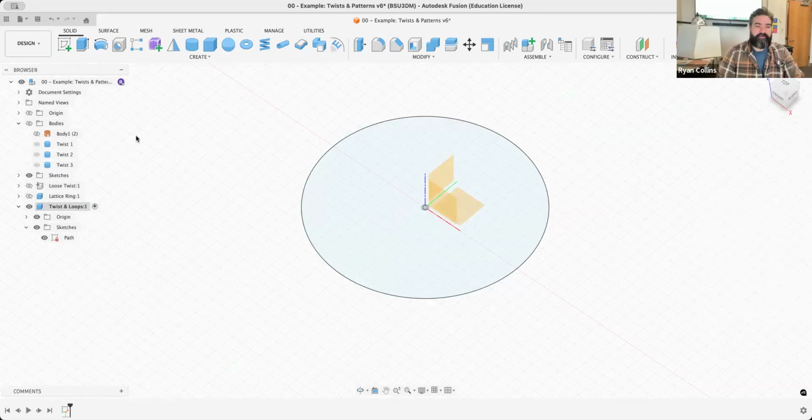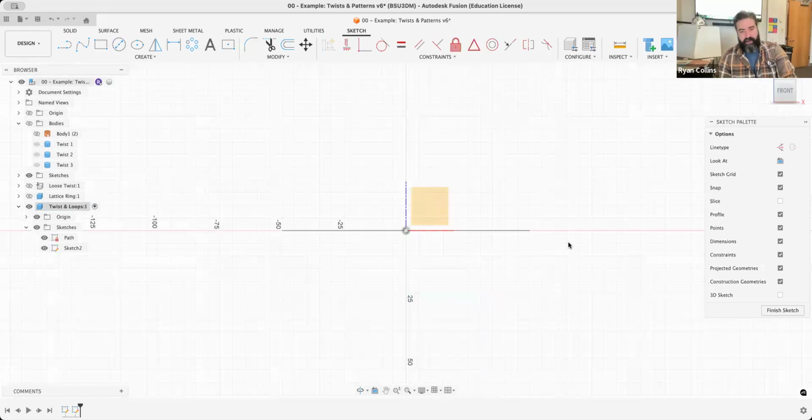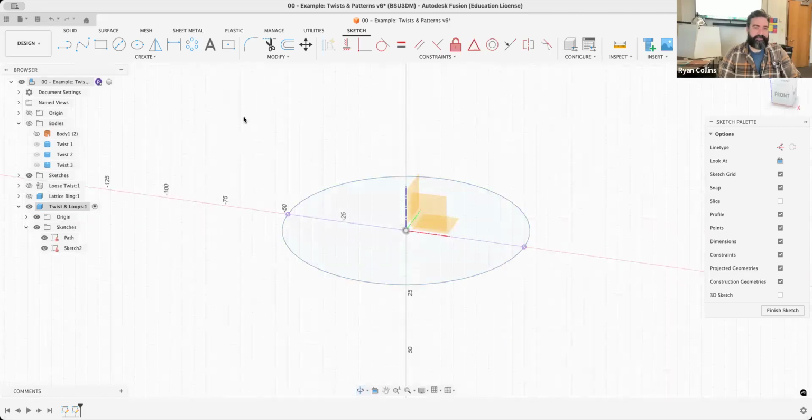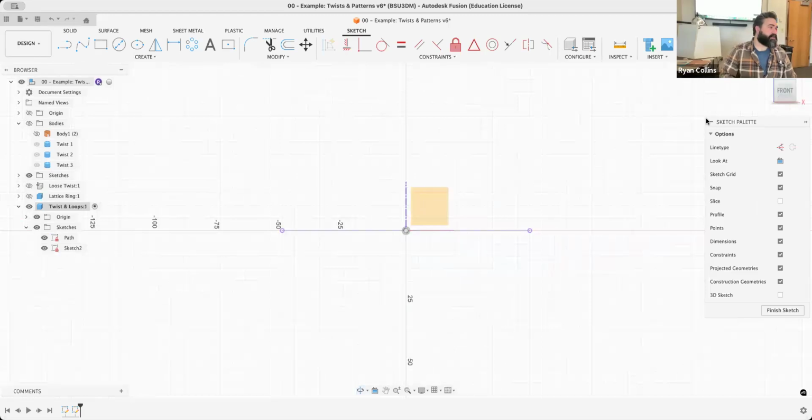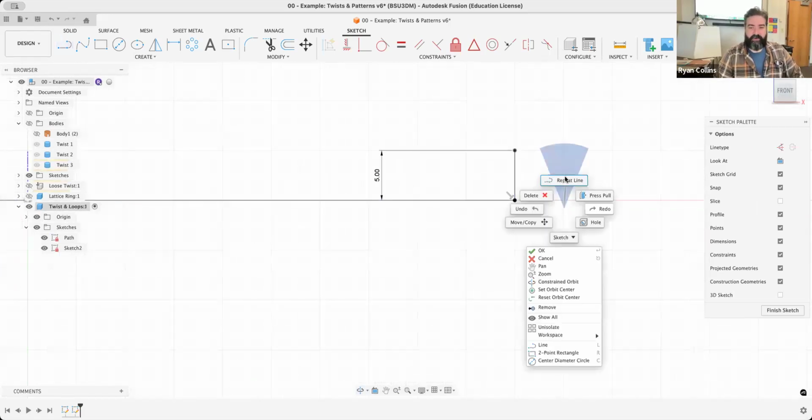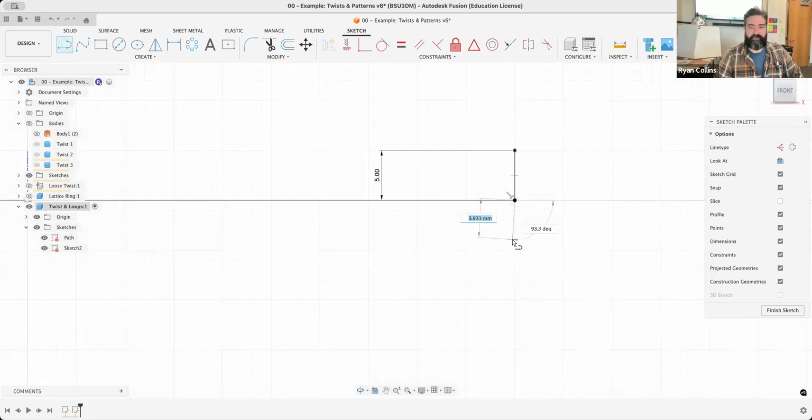From there, I'm going to create another sketch, perpendicular. This is exactly what we've been doing so far. I'm going to use project of a form just to copy that line so I get some points on the ends. That's it. All right. Now what I'm going to do is so far we've done like twists and things like that using revolve by using a solid, or rather using an enclosed sketch. In this case, I just want to use a single line. We'll go straight up 5 millimeters, sure, just because that seems reasonable. We'll do the same going downward just so that way I can have two of them if I want.